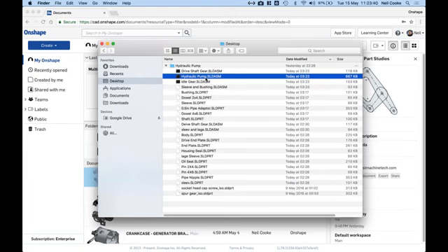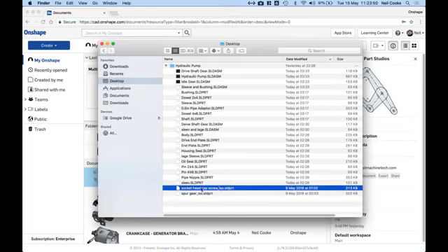However, if you don't have access to SolidWorks, but you do have the actual files, you can create your own zip file. Notice here that there are toolbox parts in here, because this was originally created from a Pack and Go, so it automatically picked up the toolbox parts. So do bear that in mind.